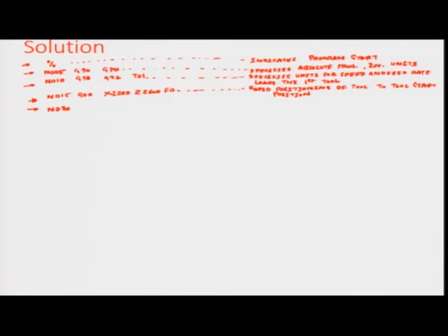So, after the rapid positioning of the tool to the tool start position, which is X2200 and Z2600, we want to now position the tool to remove or shave off the first cut, which is 0.1 inches of part diameter.